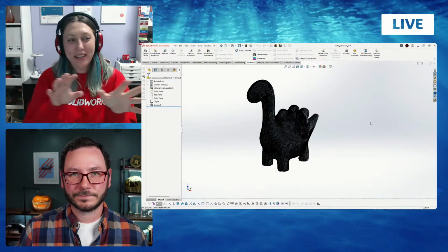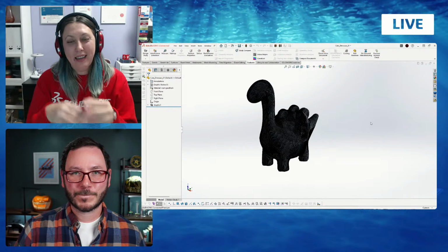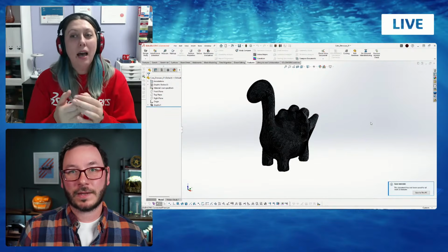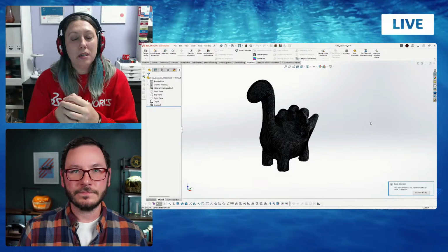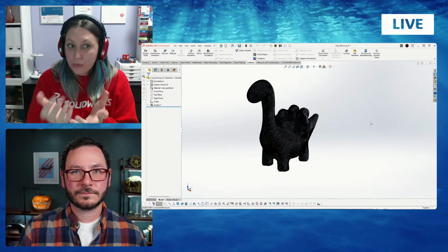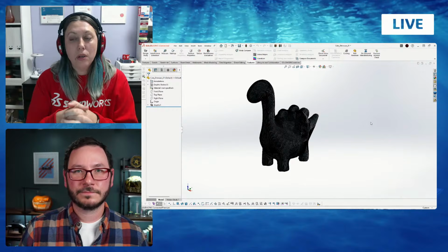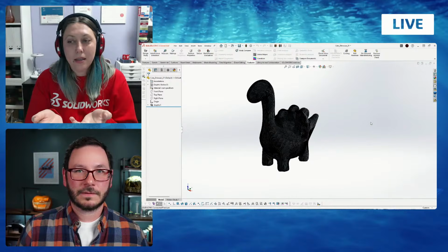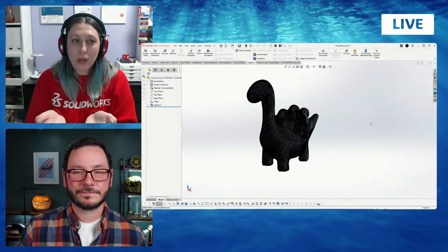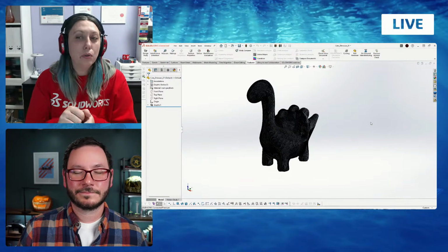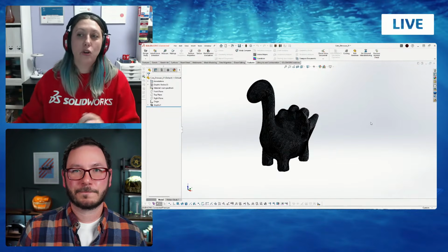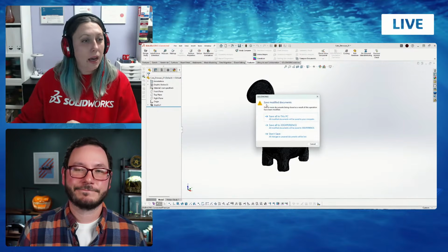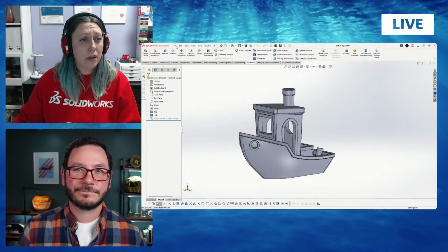Right and wrong. Okay. So you can convert graphic body into solid mesh, not into solid body the way it is. The solid body is actually a very strange format, I would say, for STL, because who would like to have every single triangle as a face? I mean, you may want to do that for some reason, but usually when you translate geometry, you want it to look smooth, nice.